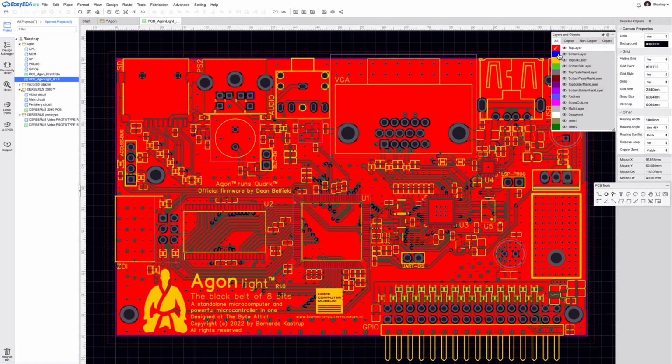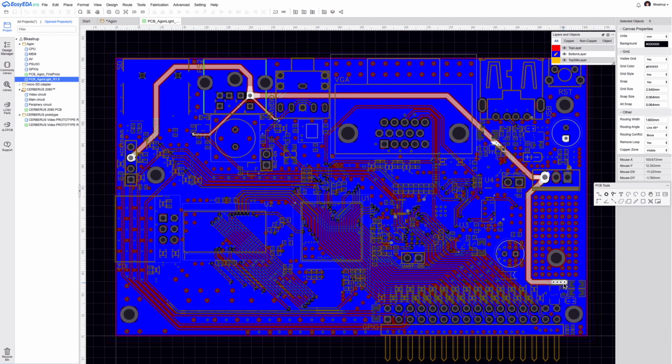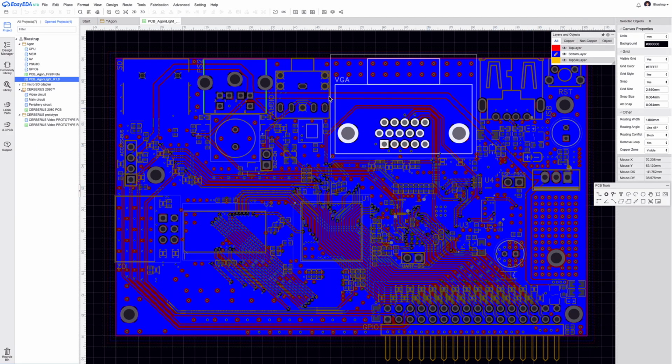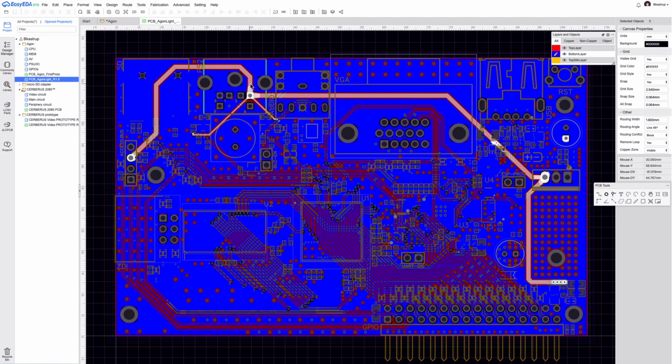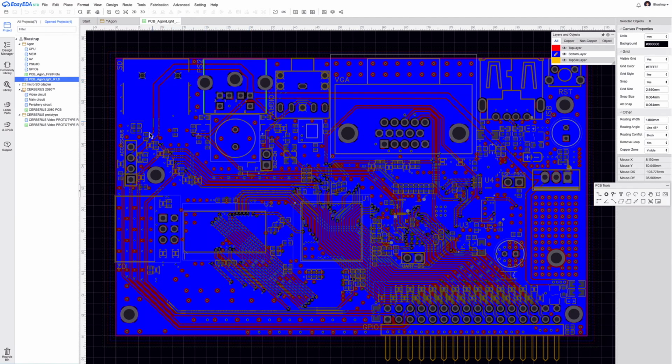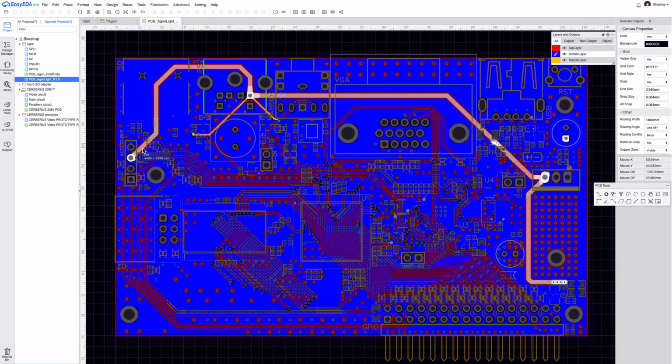And if you look at it as a whole and you highlight the 5-volt rail, maybe I have to go to the bottom layer where it's actually routed. See, this is the 5-volt rail. So whether it's powered from the USB or powered from the control port, it goes towards the same rail, where it's distributed not only to the regulator here, but it also goes to the PS2 keyboard port, which requires 5 volts, because that's the PS2 convention, and to the ACCESS.bus port, where convention requires that it be there to power whatever ACCESS.bus device you connect to that header.